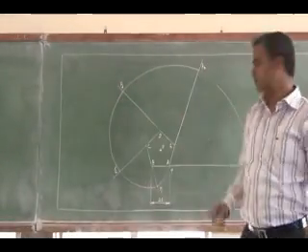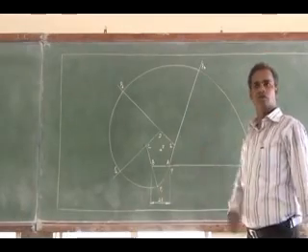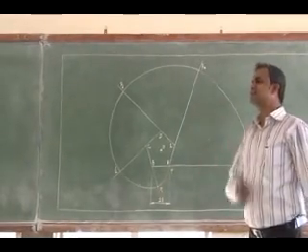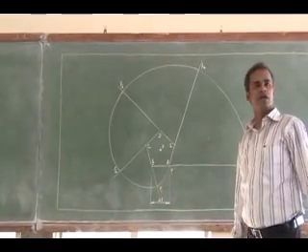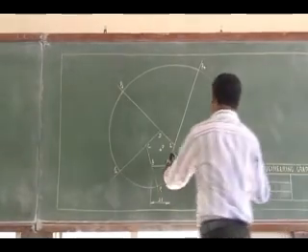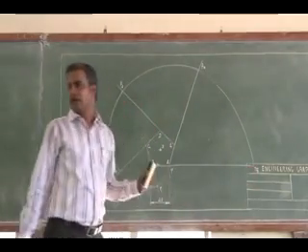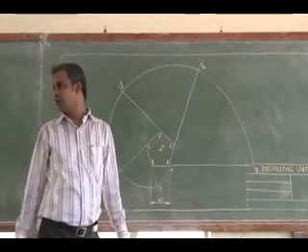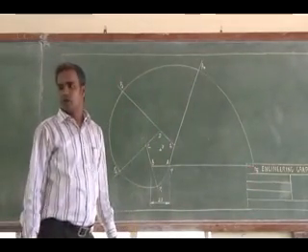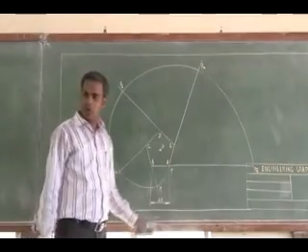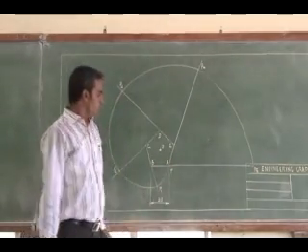The overall length of the thread which you have wound around the polygon or circle is nothing but the circumference of the polygon or circle. This length is the circumference of the pentagon of side 20 mm, that is 100 mm. Right, the circumference of this pentagon is 100 mm.